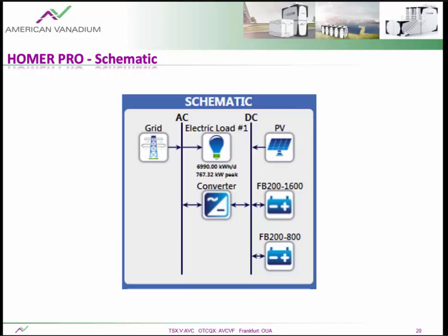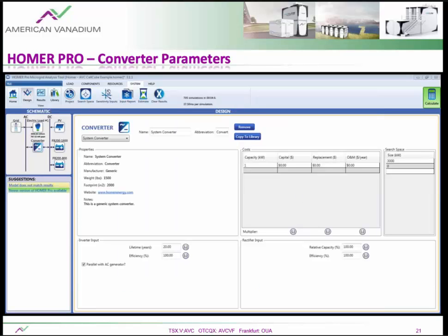That being said, when you are adding or creating a microgrid, including a PV, it does add a bit of complications to it. Because the PV system requires a converter, and there is a cost and there is an efficiency loss, I recommend using an average of the two. So, for example, if the efficiency of the converter for the PV is 90%, I'd use an average between 90 and 100%, so 95% in that case. Likewise, I'd do the same for cost.